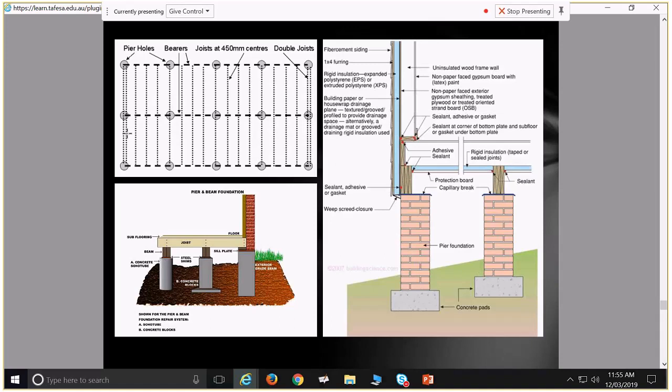Now, for some of the steel frame flooring systems, you've got bearers in the same line as your joists. So you've got, I'll draw it here like this. That's your big solid bearer, and then your joists are joined on to your bearer with some sort of joist hanger like that. That's all very much in the one plane. Or you can have systems whereby your joists sit on top of your bearers. You end up having deeper floors.